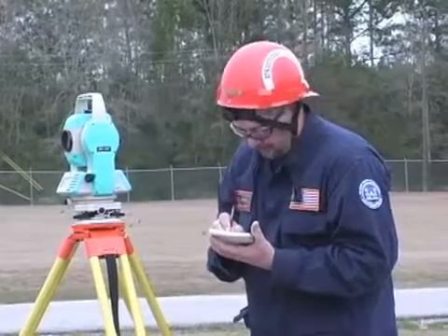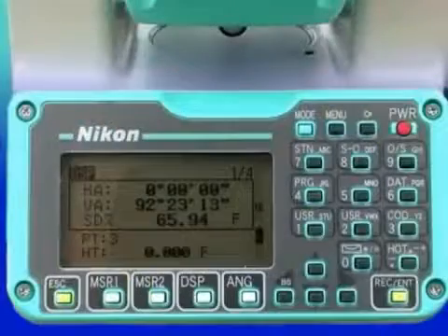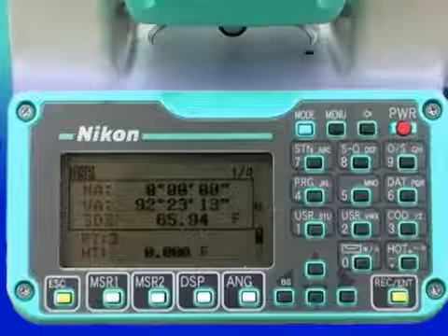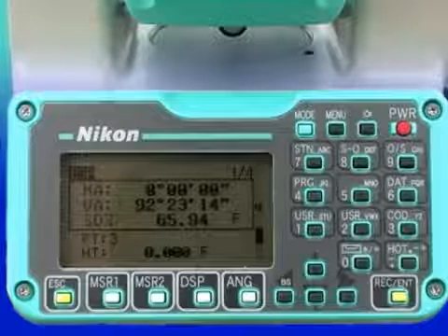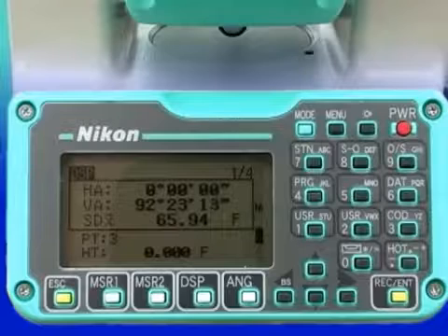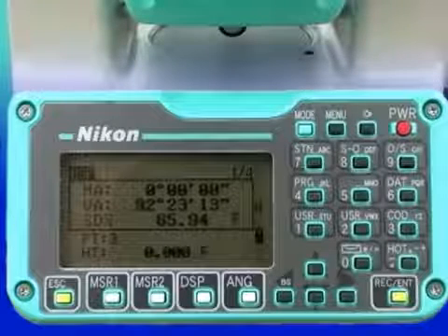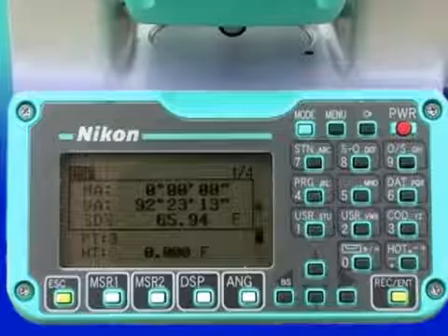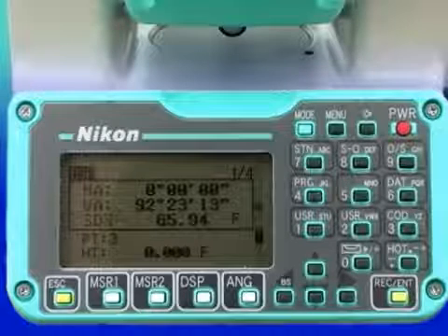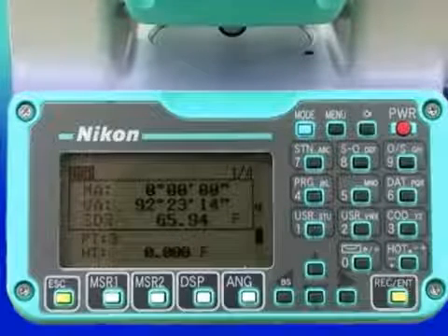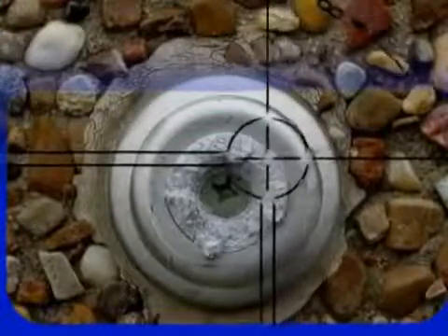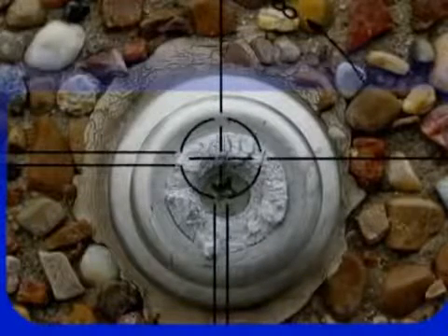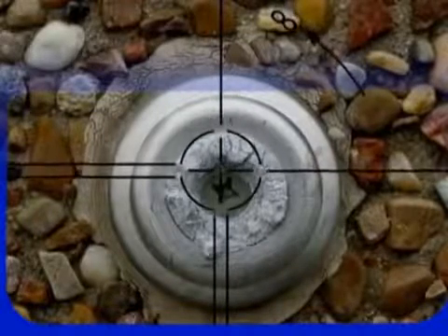Once the horizontal and vertical angle are known, the points can be monitored by turning the telescope back to the last recorded location, using the tangent screws of the instrument until the output screen of the instrument has the desired readings. After returning the instrument to the prior recorded horizontal and vertical angle settings, the object is sighted through the telescope, and movement can be immediately ascertained by seeing if the crosshairs of the telescope are still centered on the